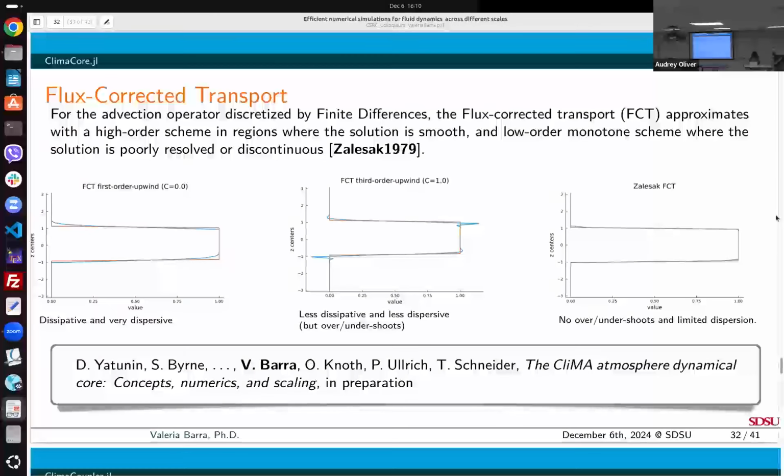I also paid some attention to linear upwinding in 1D, so in the vertical direction. So remember, in the vertical direction in this package, we use staggered finite differences. However, to overcome some of the challenges, again, for pure advection, pure transport problem, we consider flux corrected transport.